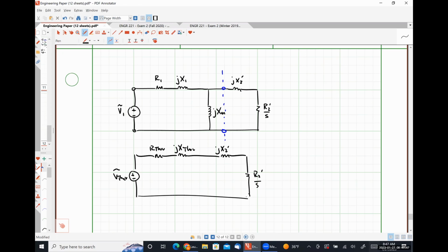So that's the Thevenin equivalent circuit, replacing something that's hard to deal with and making the overall circuit simpler. We do that all the time when we're doing small signal analysis of transistor amplifiers as well, because we have this big gnarly looking thing, but we can compartmentalize and simplify it by Thevenin equivalence.